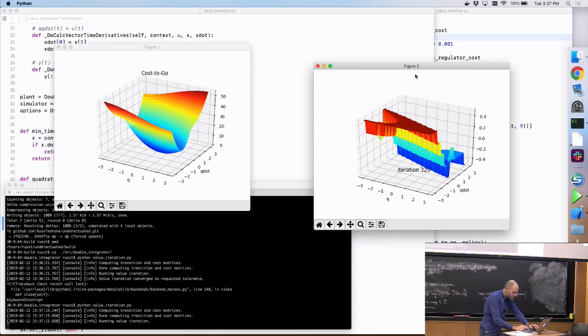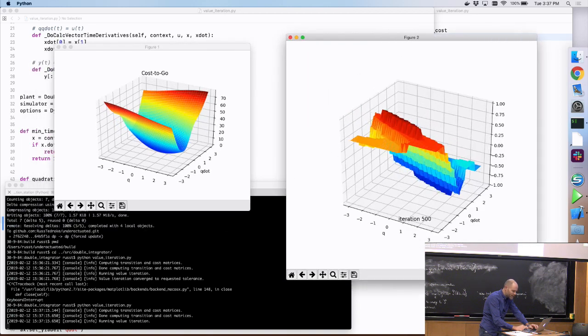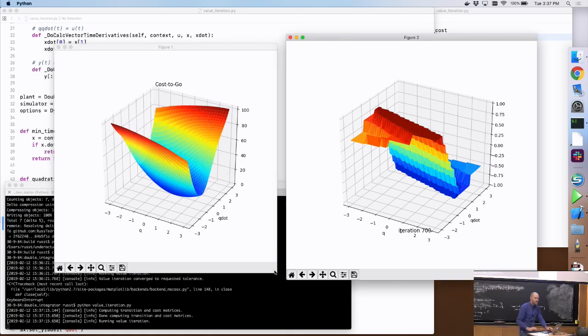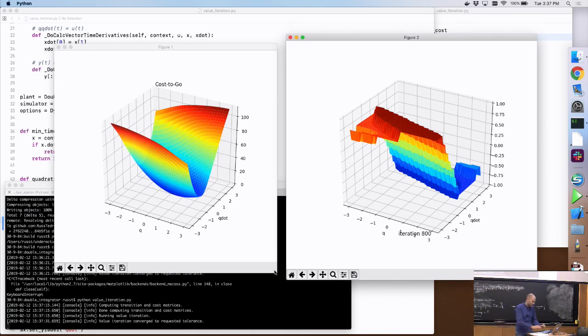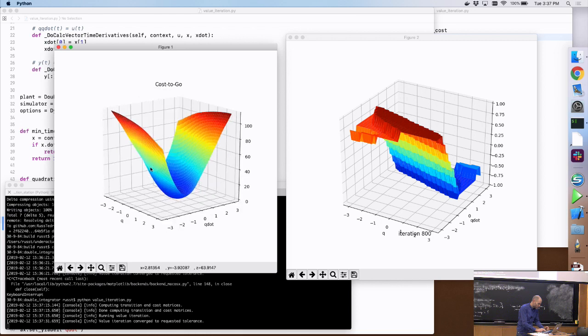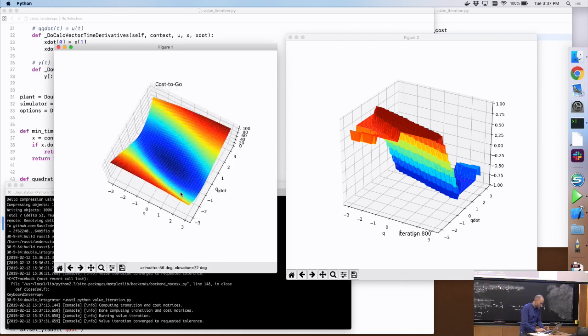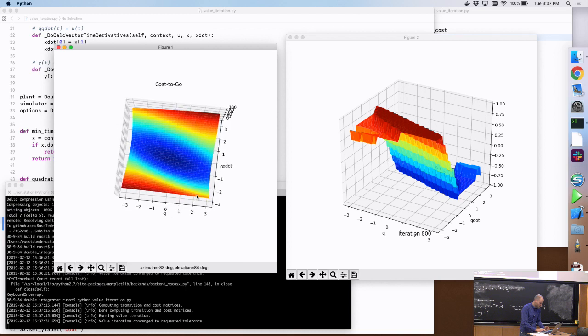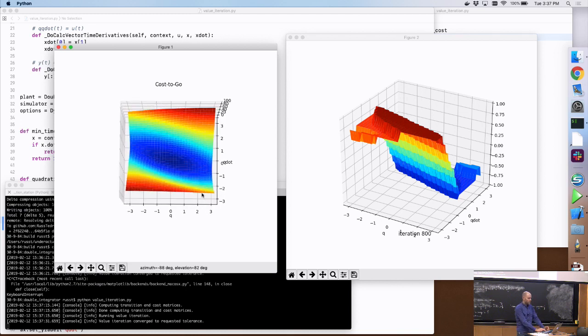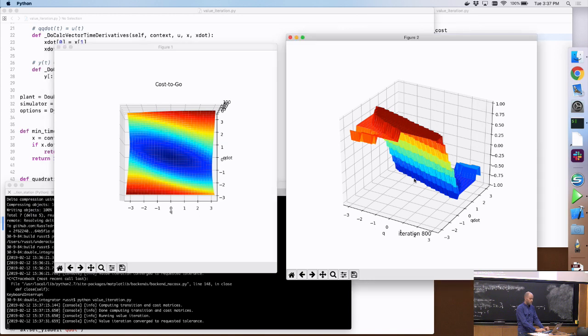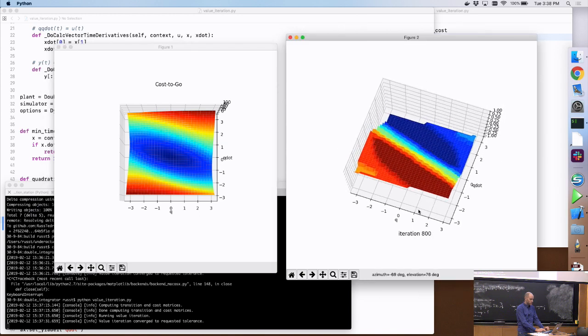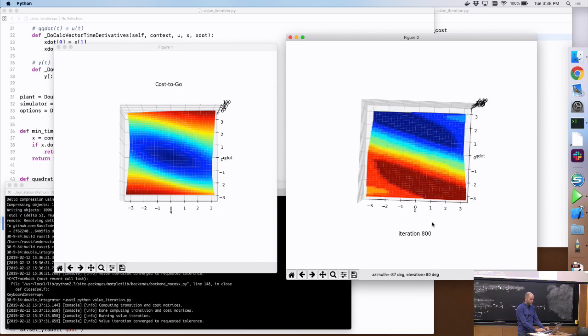Okay, so this is, what I would say is graph search, understanding the dynamics of the double integrator, okay? So the cost to go function of the double integrator takes this beautiful form, okay? We'll understand that exactly. If there were no saturations, then this would be a quadratic function, which turns out is the analytical solution for the quadratic cost. Okay, and the optimal controller is actually a simple linear function of Q and Q dot, okay?